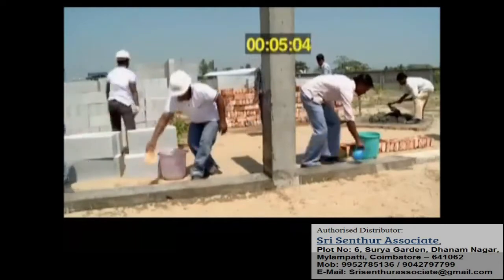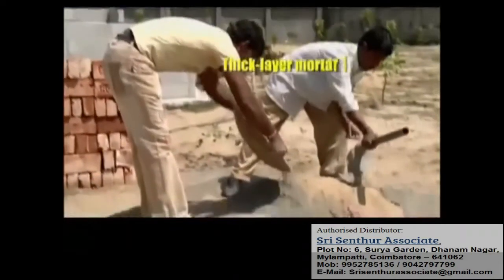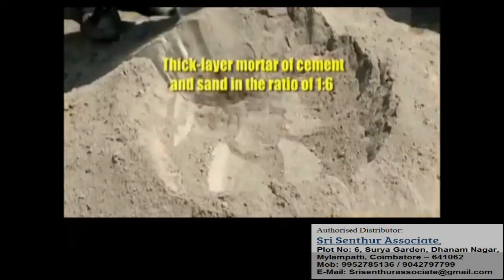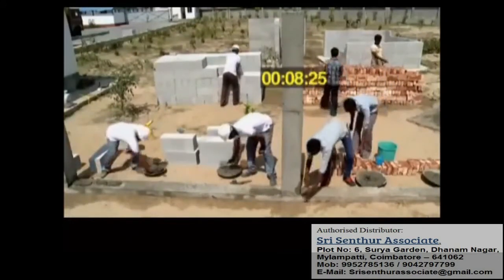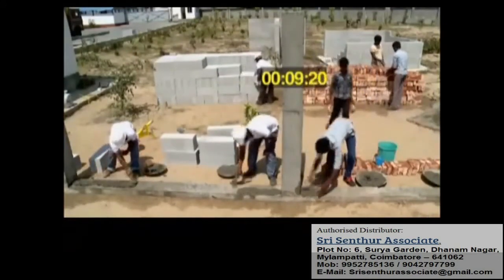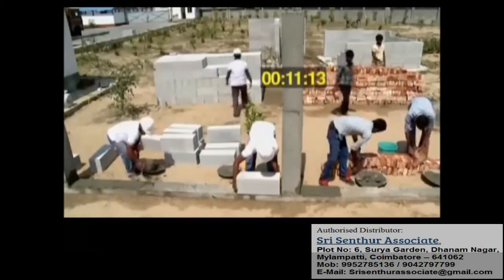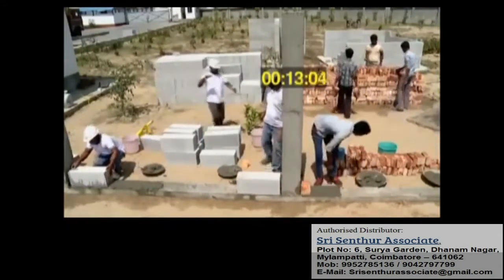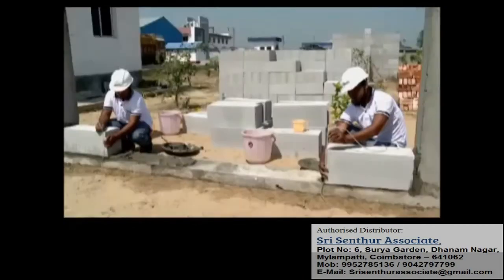After chipping and watering the foundation and the pillars, a thick layer of mortar of cement and sand in the ratio of 1:6 mixed with water is applied. As with bricks, the walls are erected by first placing blocks at the 2 corners. A water level pipe is used to ensure that the corner blocks are placed in a straight line.